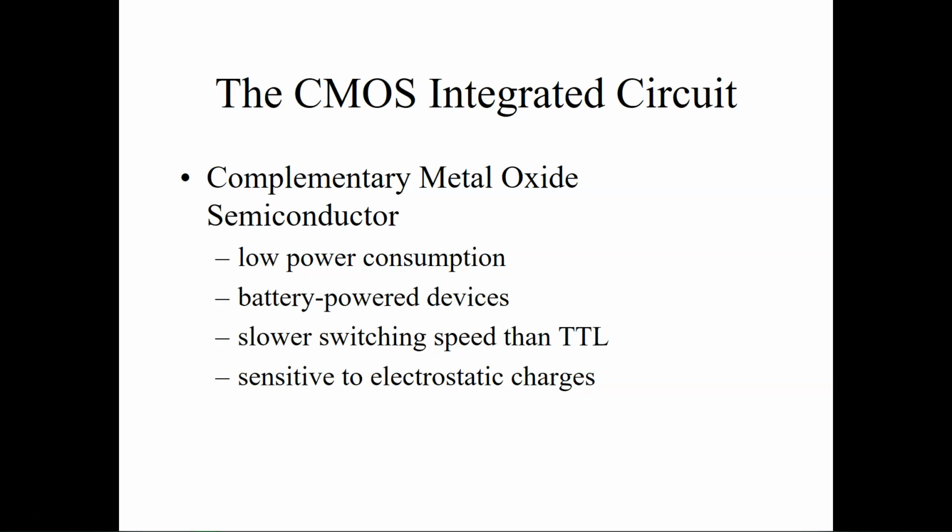So anytime you work on anything electronic, technically what you're supposed to do is make sure that you're free of any and all static. Here in the wintertime, that's a little harder than during other times of year, right? Yes, ma'am. Because other times of year we have enough moisture in the air to help absorb that static electricity and dissipate it. But here during winter, not so much.